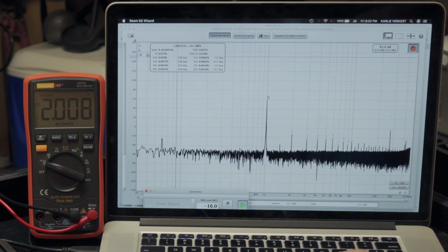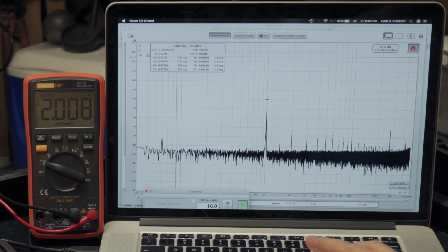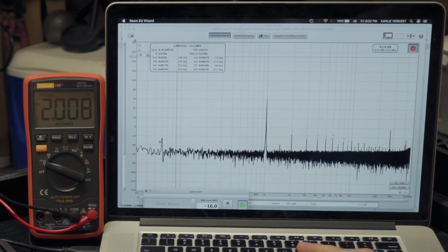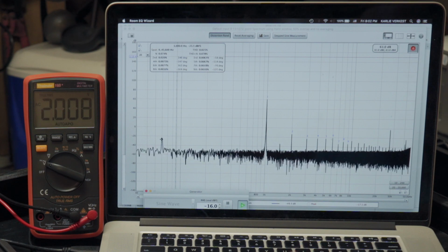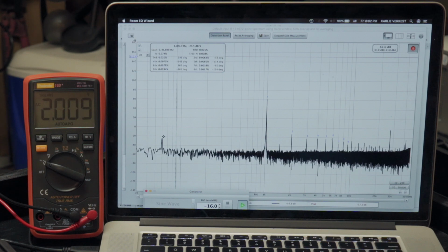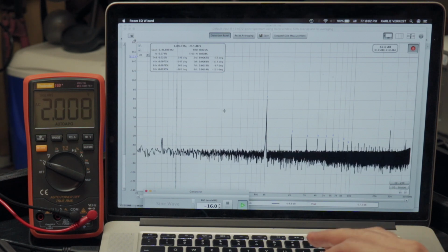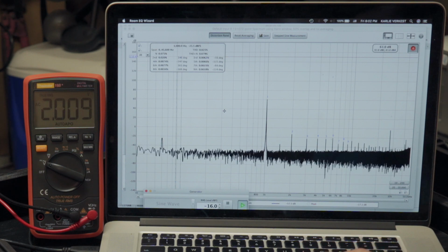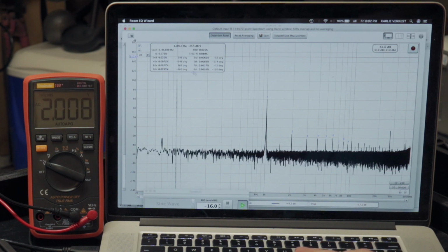But you can see versus 1 watt, we're here at 60, and this is down here at below -20, right? And so we're still better than 80 dB signal to noise and hum versus 1 watt. That's not bad. That's pretty good. Yeah, I mean, I've seen better, obviously. Most of my amps are a lot better than that, but that's perfectly reasonable. I mean, the noise in your room is going to be like 40 dB probably. So this is all down in the weeds as far as listening goes. All right, so that's looking good.